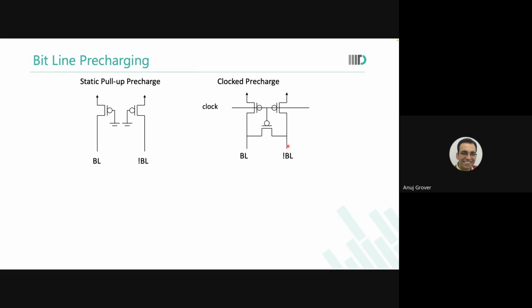See, until now, when we are saying pre-charge has to happen at the end of the cycle during the reset operation, at that time you're only impacting T cycle. But as soon as you start to pre-charge at the beginning of the cycle, there's a possibility to impact access time also, TCK to Q. So now you need to really size up the pre-charge and ensure that it happens very fast before the wordline arrives. So unless you are sure that speed is not a concern, access time is also not a bother for you, you would want to pre-charge at the end of the cycle.